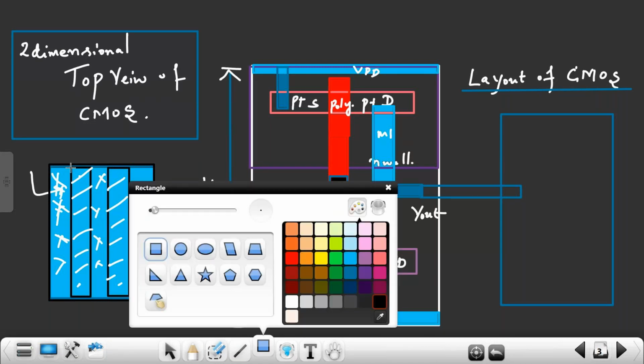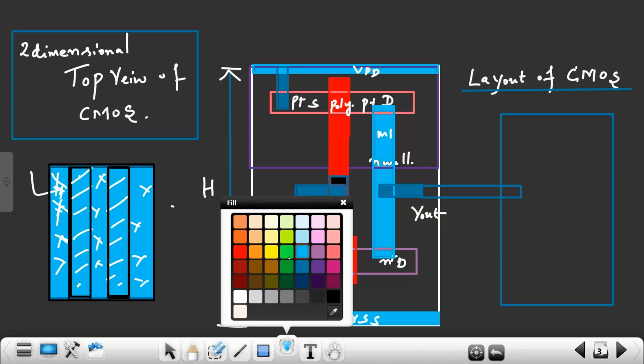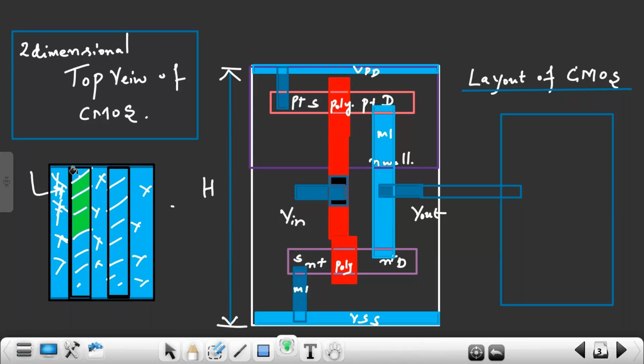They will cover it with mask like this, wherever I want to retain metal layers. Cover with mask. Remaining regions you treat with high concentrated acid. So in the remaining regions the metal layers will be removed. Only in this region I will be having metal layers.